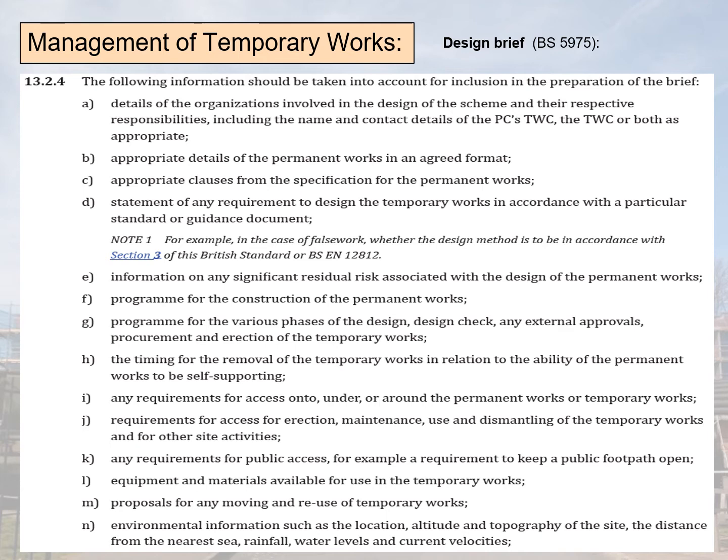Construction programme, and how the temporary works will affect it. Design phase programme. Timings for the removal of temporary works and critical loadings. Access requirements. Equipment and materials. Moving and reusing of temporary works if they're going to be repeated across the site. Location, topographical and site geological information should be included within the design report. Any services which will be interacted with or needed. Local authority requirements including noise licenses.